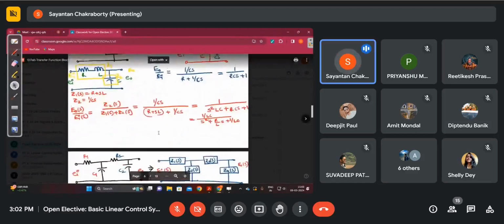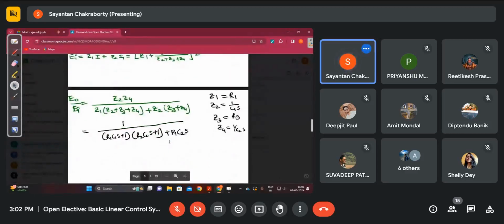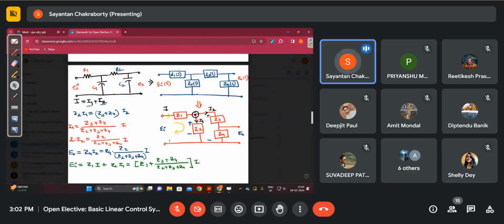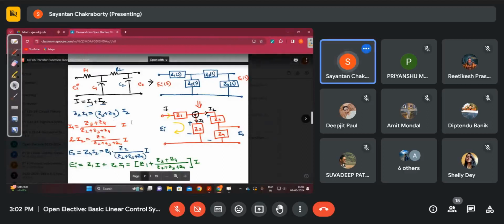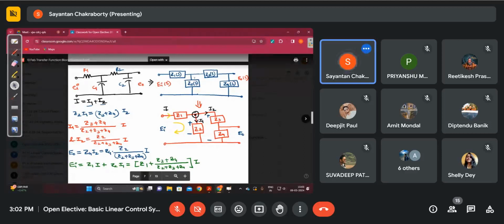By the complex impedance method we obtained the transfer function, which was a bit simpler compared to the fundamental method, which involves writing down the basic equations, taking the Laplace transform, and eliminating a couple of variables. So there is another technique, the complex impedance method, where we transform the circuit into its S-domain equivalent and then find the corresponding transfer function via simple algebra.